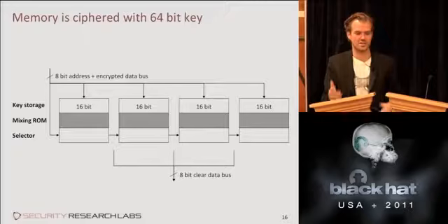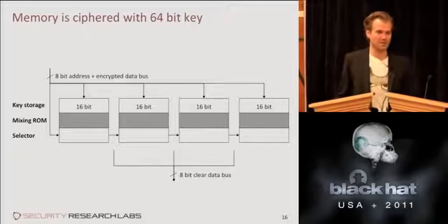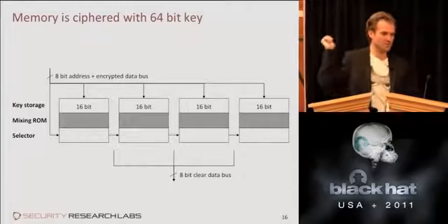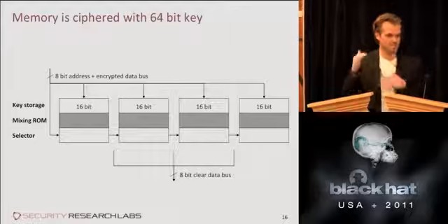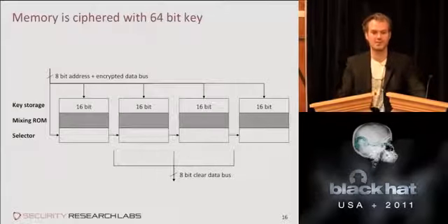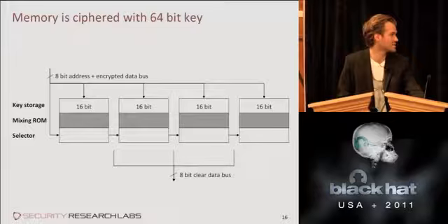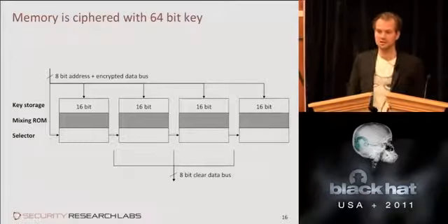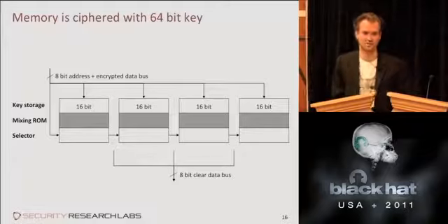There's a little chicken-and-egg problem, but it's not like the first thing the chip does is load a key and then decrypt everything else. There's a pretty substantial bootloader that's completely unencrypted, and that in some versions may even have bugs. So people could have read this out optically a long, long time ago without any of this knowledge.